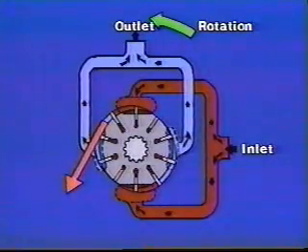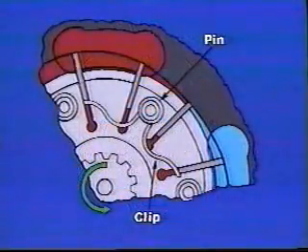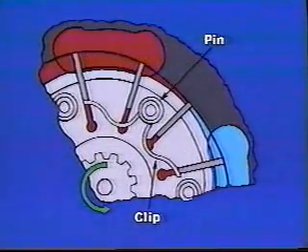Again, the big exception between the construction of a vane motor and a vane pump is the fact that the motor has to have some means, springs, oil under pressure, or both, to hold this vane out against the cam ring. We show this as the inlet side with oil coming in here to give us a torque in this direction. Flow directed to the top port and coming in here as well as in here would give us torque in the opposite direction.